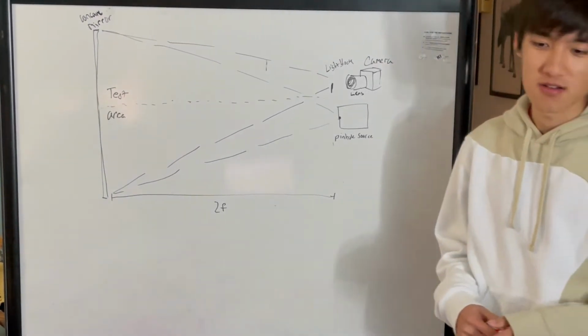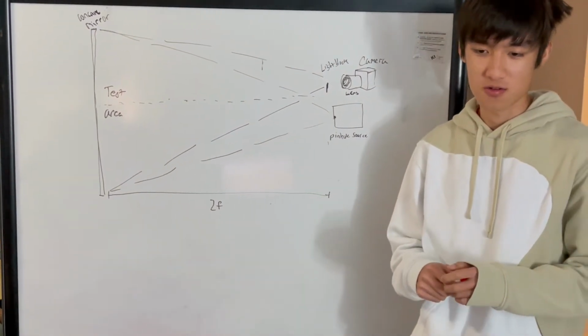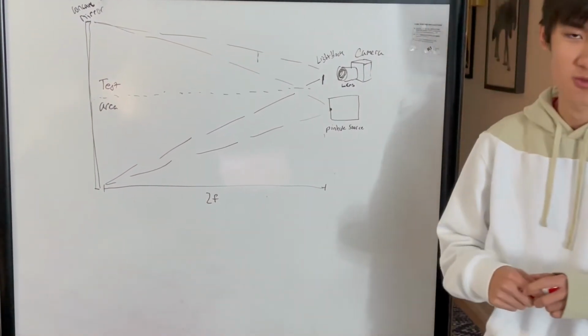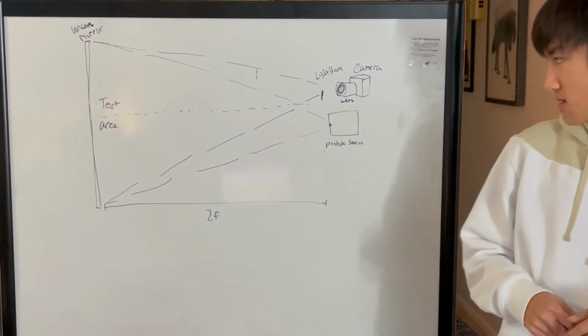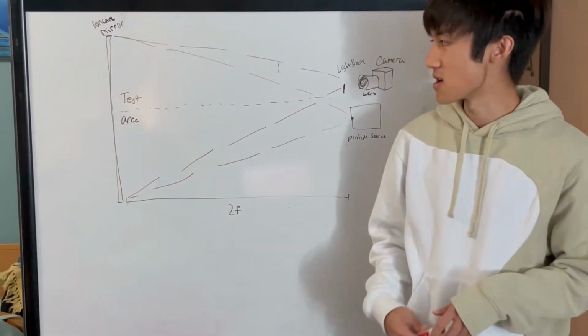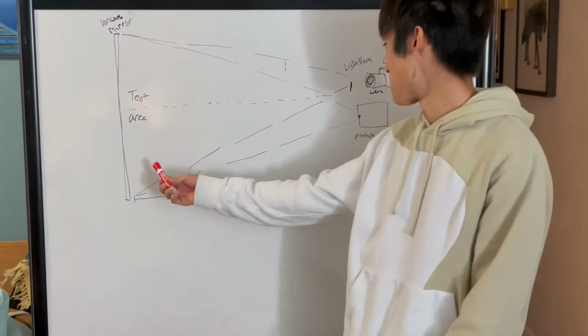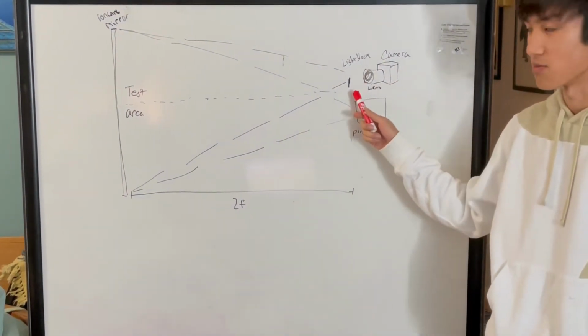In order to observe slight changes in speed and direction of light moving through hot and cool air, we must use an optical system which amplifies the effect of these changes. This system is known as Schlieren imaging, and our particular setup will use a concave mirror to focus light, a pinhole source, a camera, and a light block.